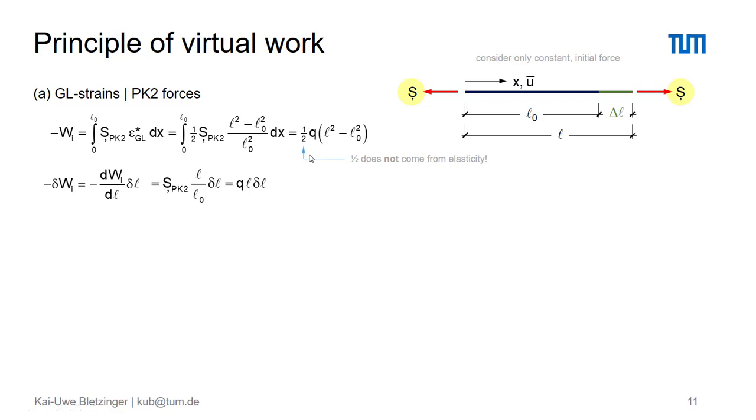And that really means that this work expression is really dealing with a large deformation, with very large deflections, so completely geometrically nonlinear, simply by the assumption that the force density, or respectively the Piola-Kirchhoff force of second kind, are chosen to be constant.